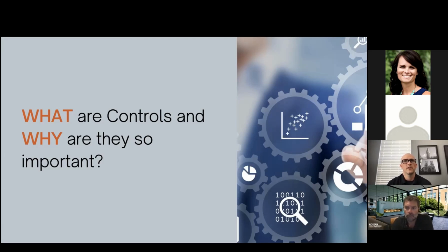They're not necessarily explained correctly to owners, end users, and things like that, and the actual importance of controls. So what we see is a lot of value engineering happening when it comes to controls, whether it be points taken out, sensors removed, non-essential, non-code-minimum things being removed from systems, which is great for first cost. But it really adds up and will destroy that first cost almost within the first year in terms of not having those controls.